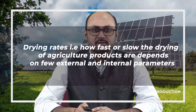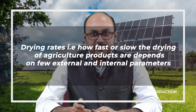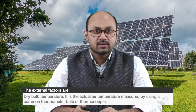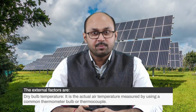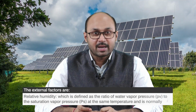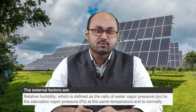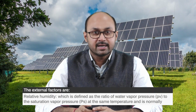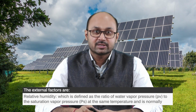Drying rate, that is, how fast or slow the drying of agricultural products is, depends on a few external and internal parameters. The external parameters may be dry bulb temperature, which is basically the actual air temperature measured using a common thermometer bulb or thermocouple. And relative humidity. Relative humidity is one of the very important parameters. If you want to discuss the drying process, then relative humidity is a very basic parameter, which is defined as the ratio of the water vapor pressure to the saturation vapor pressure at the same temperature, and is normally expressed in percentage.